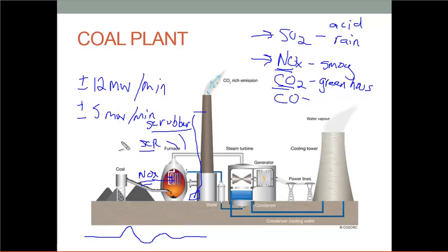And so, if you've got 100 megawatts of solar generation and a cloud bank comes through and you lose 50 megawatts of that pretty quickly, you're limited in what you can do with your steam units. Your ramp rate on the steam units, you're limited in what you can do to respond to that, right? So that becomes an issue.